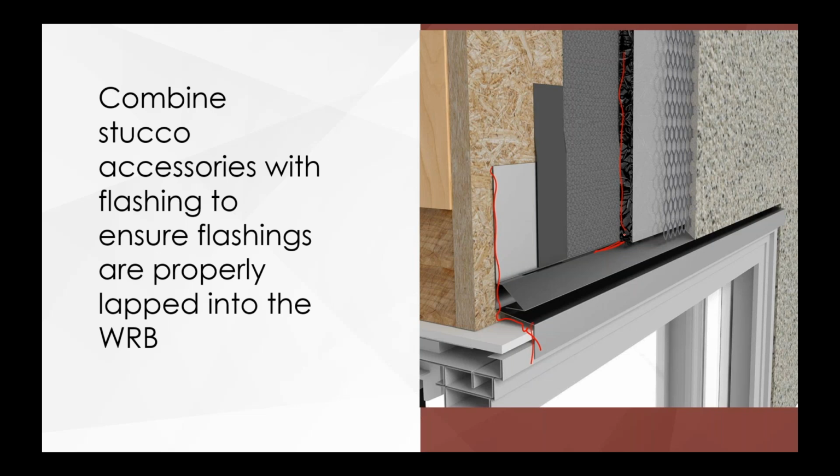Now, look at it this way. You've got a stucco assembly. You're going to have cracks here and there. You're going to get some water in there. Getting water in there is okay. Incidental water is absolutely okay. That's what you've got a water resistant barrier for.